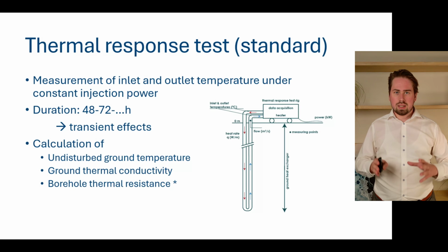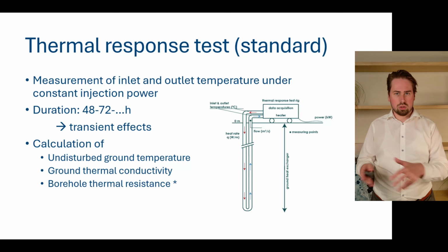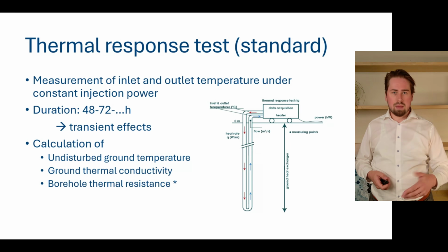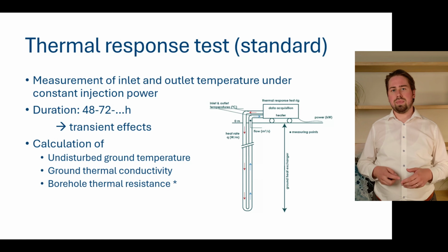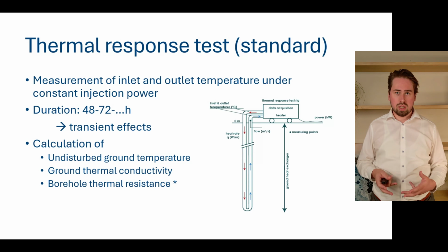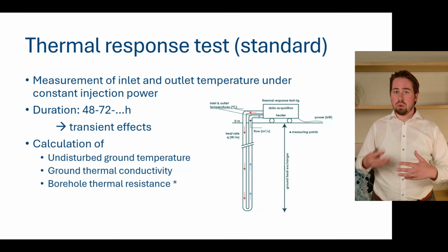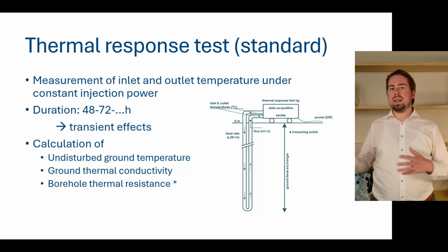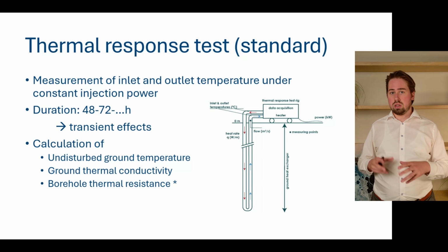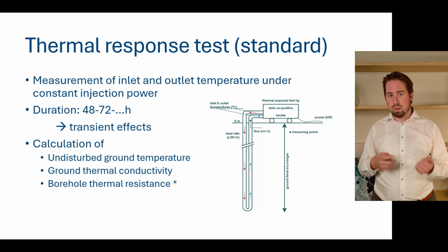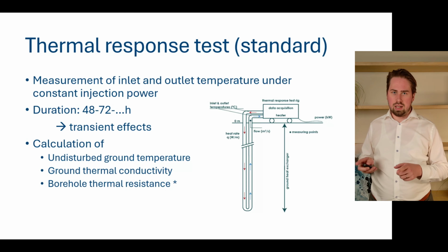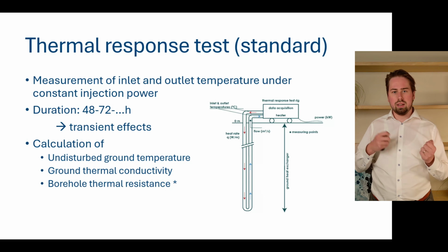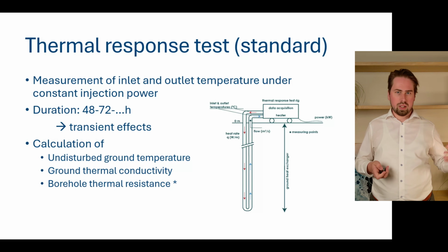So a thermal response test is basically a test you do on an already installed borehole. So you go to your project location, you drill the borehole with the same diameter, the same depth, the same grout, the same heat exchanger as you would do for the rest of your project. You wait a couple of days until the grout is hardened, and it's again in thermal equilibrium with the rest of the ground. And then you install a mobile data logger, which is just a data logger, circulation pump, temperature sensors, and electrical heater. And then you start heating up the fluid, you measure the inlet and the outlet temperature, and this you do for 2, 3 or more days.